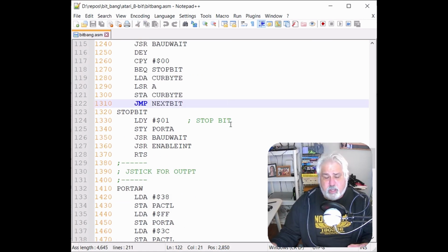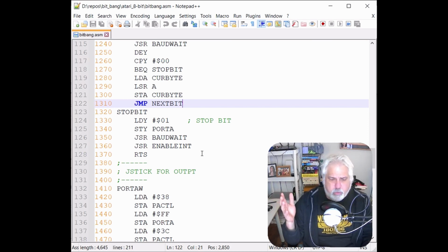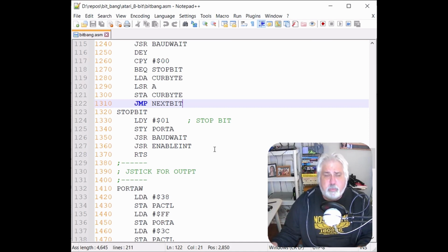So to try to get the timing, if you're not familiar, you have interrupts, non-maskable and maskable interrupts. In most systems, non-maskable you can't do much with. Those are going to be very highly important, prioritized interrupts needed by the system. Maskable interrupts, or interrupts you can stop, you can basically turn off so that they don't impact what you're doing. And that's what we needed to do in this case because we wanted our timings to be fairly accurate.